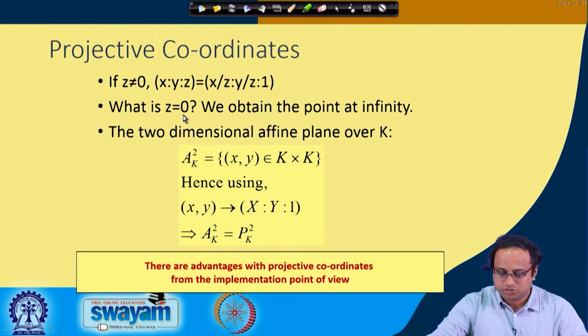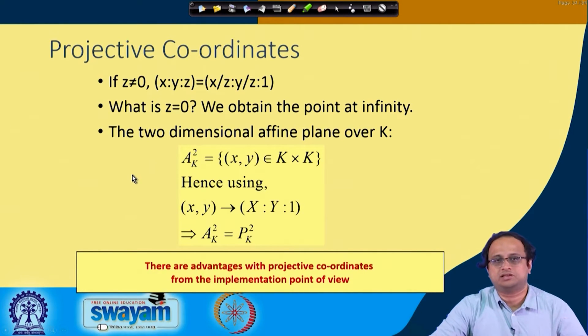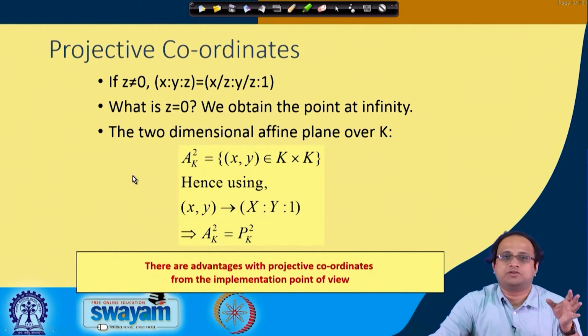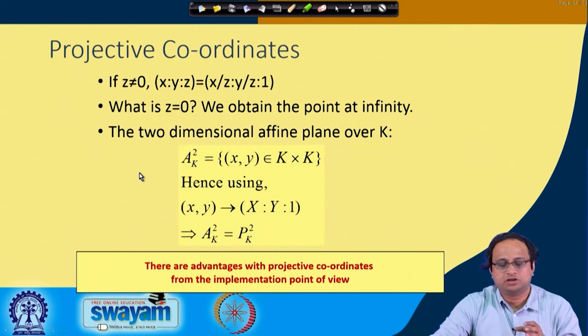Okay. So let us try to see how we can do this computation. Of course, we have to see the advantages, and only if it is advantageous, because there will be some increase in computations also when you are converting from the affine coordinates to projective coordinates. What you have to see is whether the increase or the cost that you are paying is giving you benefits. Okay. So whether you should go into projective coordinates will depend upon your m to I ratio. That means the cost of the multiplier compared with your inversion circuit. Okay.